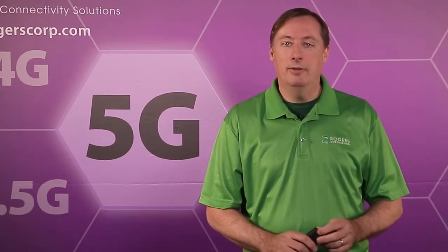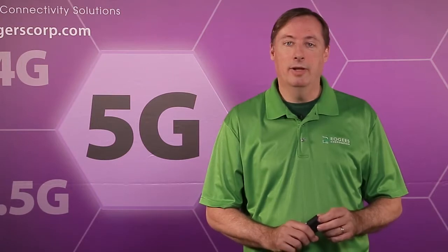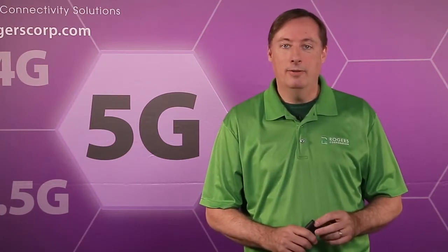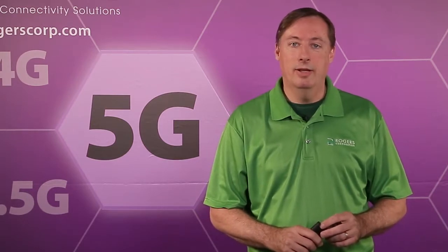So to begin with, let's talk about insertion loss. As most of you know, insertion loss is made up of four different components. There's conductor loss, dielectric loss, radiation loss, and leakage. I'm not going to be talking about leakage losses today, and also not going to talk about radiation losses because that's more design specific. I'm going to be talking mostly about the dielectric losses and conductor losses.